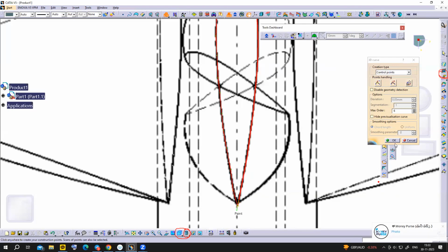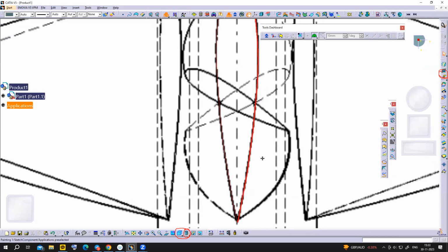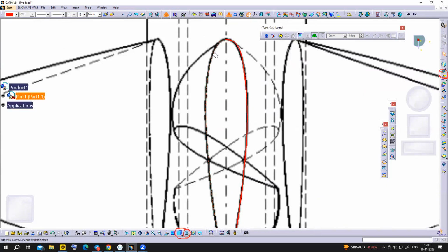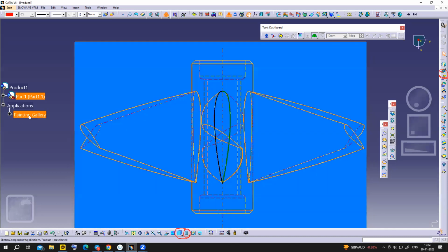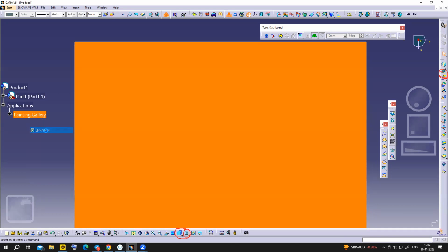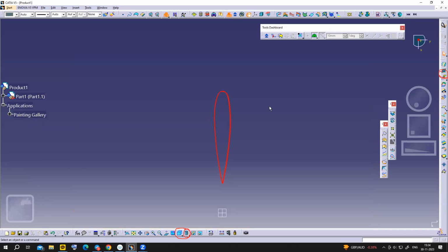Okay. We have two curves which are perfectly matching with the aerofoil, the bottom aerofoil surface. And you can change the thickness of this line to 0.7. So tracing the curve is finished. And you can hide this picture. Don't delete, hide. Make sure that you do not have any extra projections here, because I already gave tangent, so there is no extra projection.